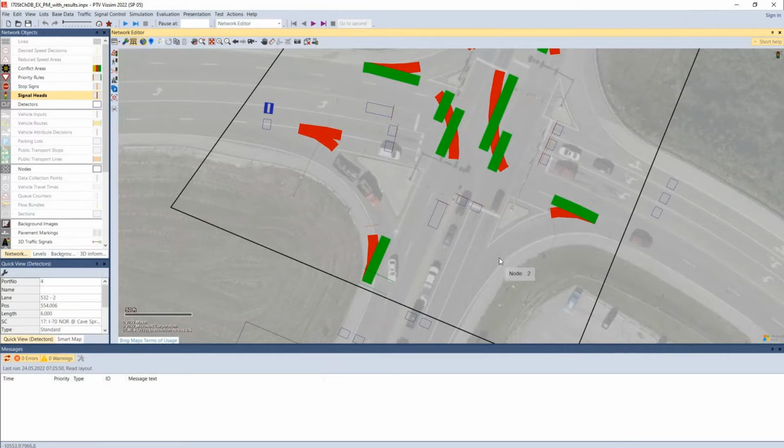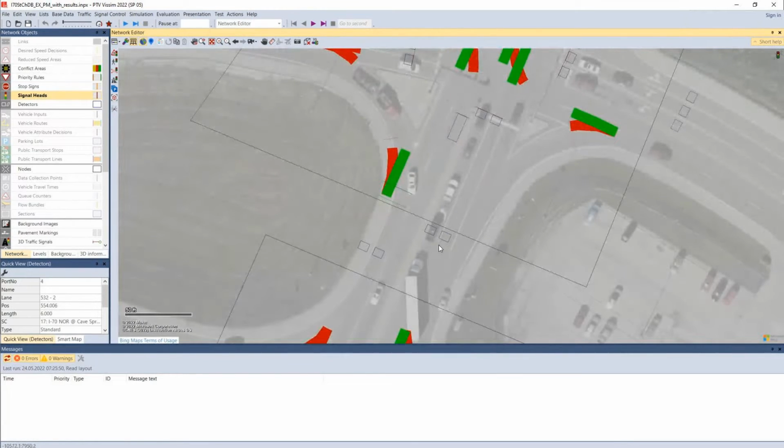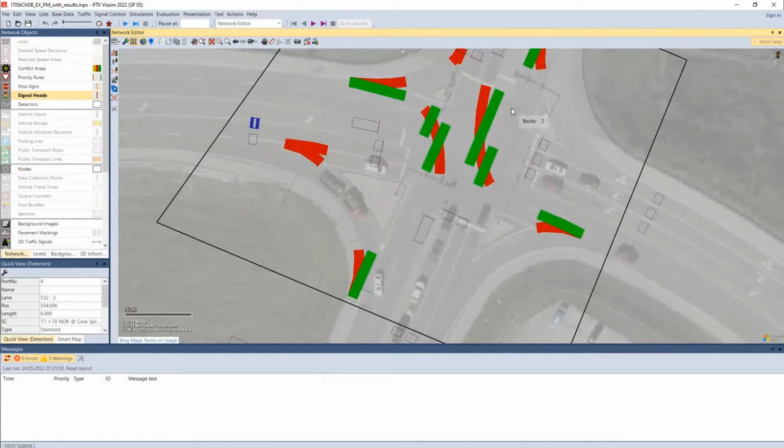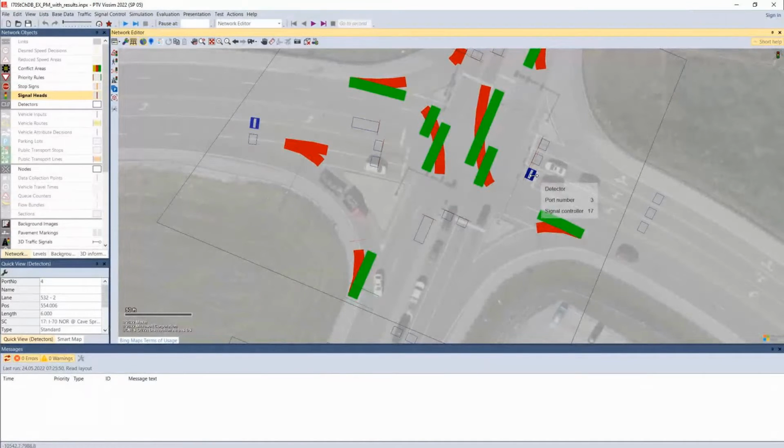So if we look at the aerial underneath, we can't really see induction loop detectors in the pavement where these detectors are, but maybe there are video detectors or something like that on the signal head itself. And this is the zone that they are calibrated to detect a vehicle. And so the detectors themselves should be recreating that detection zone. And so that's what you'll be looking for there.